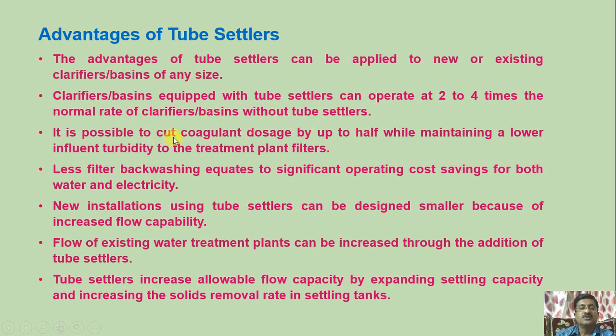It is possible to cut coagulant dosage by up to half while maintaining a lower effluent turbidity to the treatment plant filters. Less filter backwashing equates to significant operating cost savings for both water and electricity.